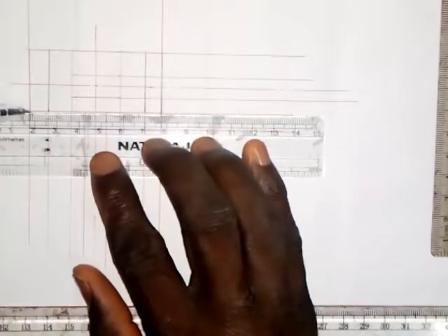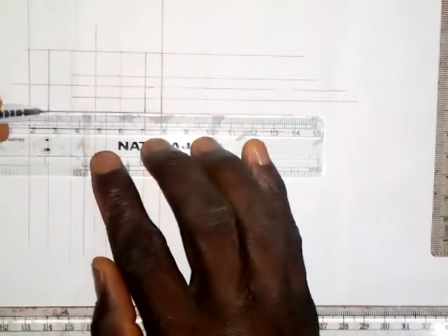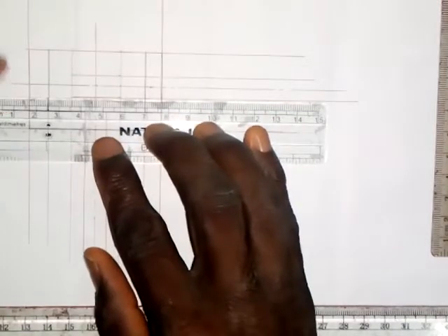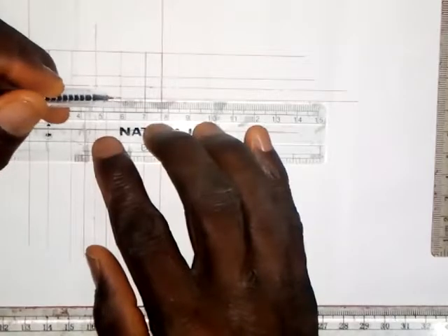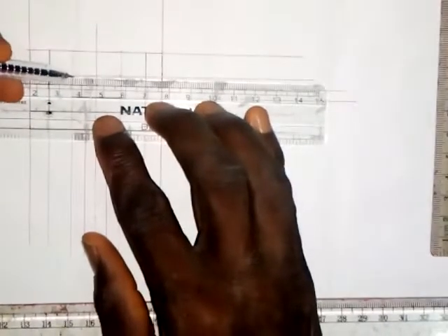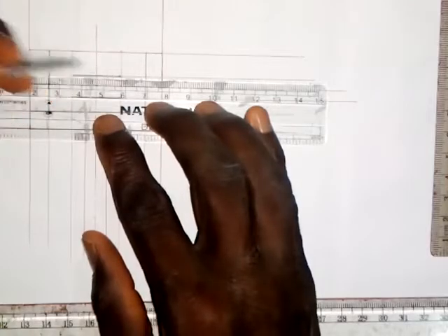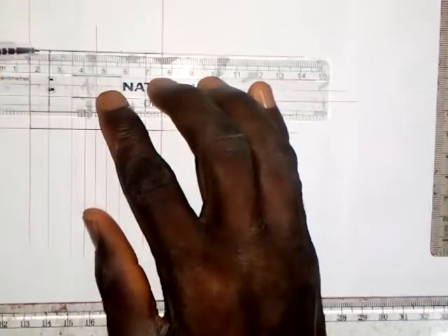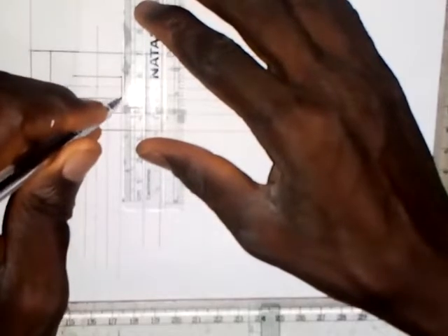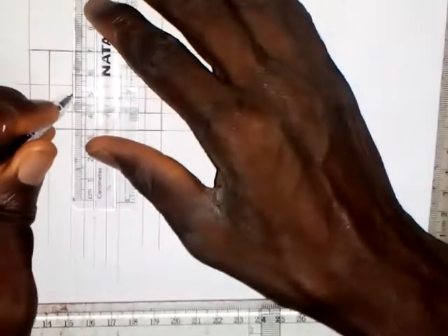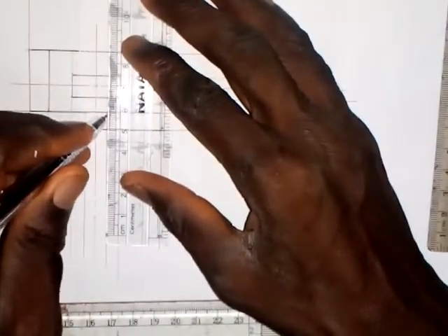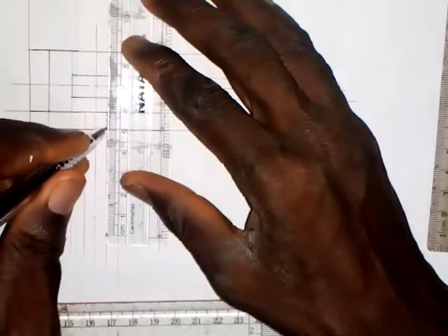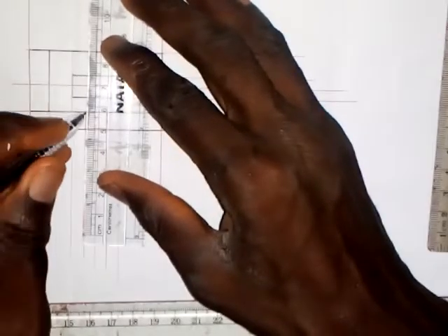I will draw this horizontal line. All right, and then the rectangular hole that we have in the middle, there it is. And then this also, I'll make this line a thick line from here to here. All right, so you can see that the shape is coming out. This is the width of this rectangle, and also the width here. Okay, for the square that we have there, it is hidden from us in the front elevation. I need to put short dashed lines here.